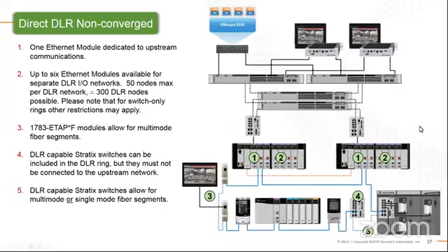So this is a bit of a busy slide, but I wanted to add these in as recommendations on how we would look at an overall architecture. So for anybody that hasn't seen redundancy, we deal with a 2 chassis-based system. So you would have your controller, your redundancy module connected via fiber. It is 2 fiber drops. Essentially, you can design 2 separate paths for your fiber.